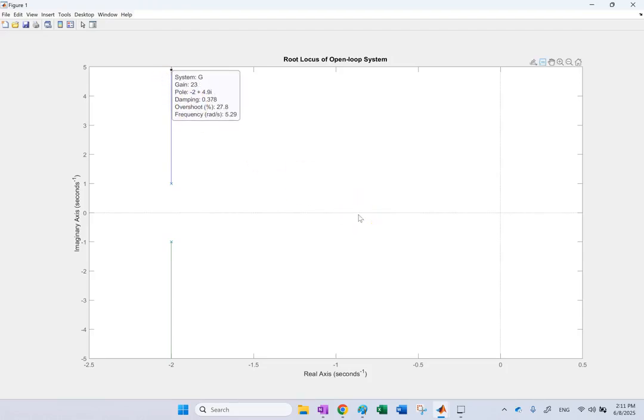That's interesting. The maximum this one did is somewhere close to a gain of, if you can see, a gain of 23, but it's smaller than that, right? Or bigger than that. Because look at my damping ratio, it is 0.39, 0.37. It jumped from 21 to 23, so if it doesn't show it, but if you want, you guess probably it's around 25. It's around 25 that you get that intersection point.